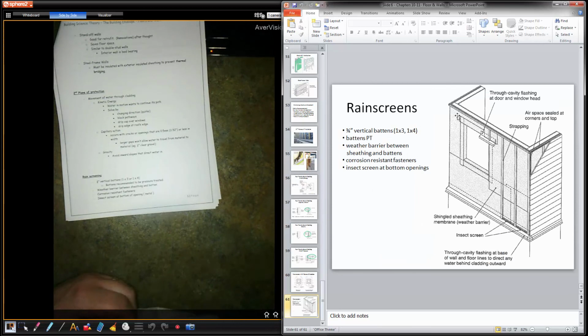So having a strapping across the top would then make it kind of like a negative pressure. So it's kind of a neutral, and so it's not really well ventilated. Right? So basically it's going to take a little while for that to dry out because air goes in, it can't come out. If air goes in and is allowed to come out, you'll get good airflow. It'll travel through there quickly. But if air goes in and hits something solid, it's kind of stopping. So that's kind of like a negative pressure.